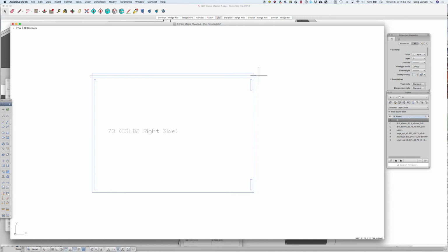So we overcut by the full diameter of the bit that's specified in our table for pockets, because this is a pocket ultimately. All these are pockets. They're on the pocket layer, and they all happen to be using the same tool, the 3/8. The depth happens to be 3/8, and this is the name of the bit. So that's what you'll see.